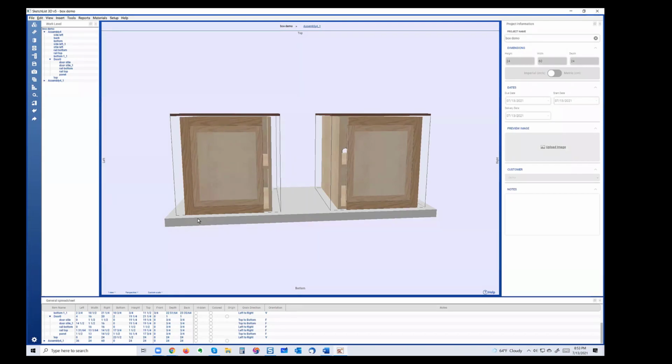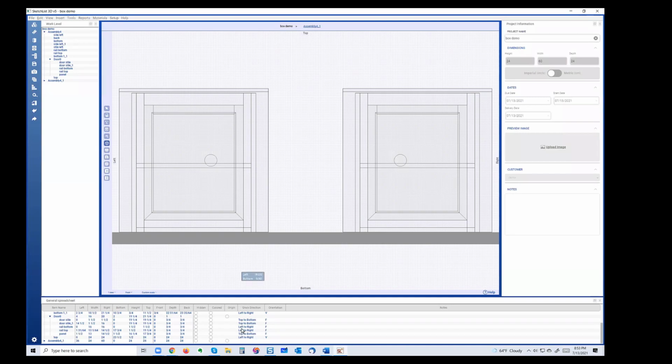I'm at the project level. You see the floor. If I come in, I do shop drawings, do a new shop drawing. I'm at the shop drawing level. I can only dimension the assemblies. I can't go into an assembly and dimension because I'm at the project level. So I can dimension the lines 24 by 24, and I can go in this tool and enter the points, like here, the distance between the assemblies, but I can't go into an assembly and do anything because that's the thing about where I am in the nest.